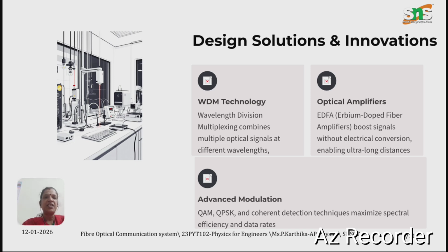Here we can see design solutions and some innovations, that is WDM technology, wavelength division multiplexing, which combines multiple optical signals at different wavelengths. Next is the optical amplifier, erbium doped fiber amplifiers, called EDFA, which boost the signals without electrical conversion, enabling ultra long distances.